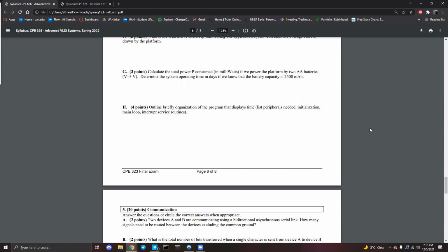As mentioned, you set timer A to generate an interrupt every 100 milliseconds, so figure out the numbers you want for that. He explicitly says he uses up mode with MCLK divided by 8 as the source clock, and he ends up putting the value 12,499 in CCR0, right? Then you have to go to the LCDA and do the MUX thing. But since we never use the LCD controller, we would get smashed on that, which is why this question probably won't show up.